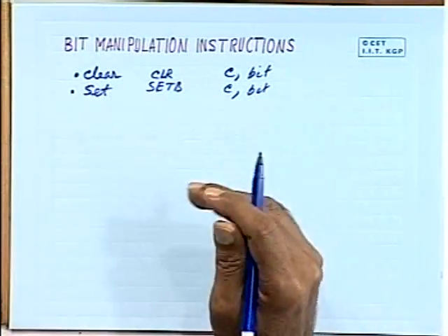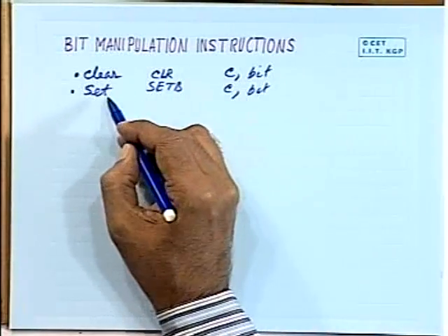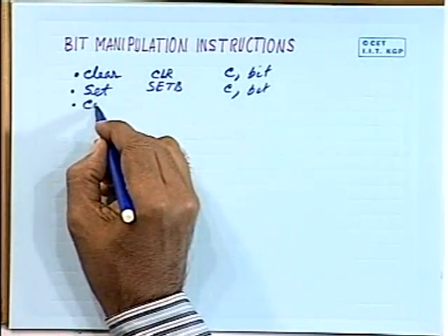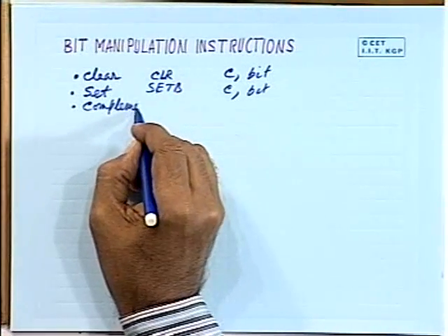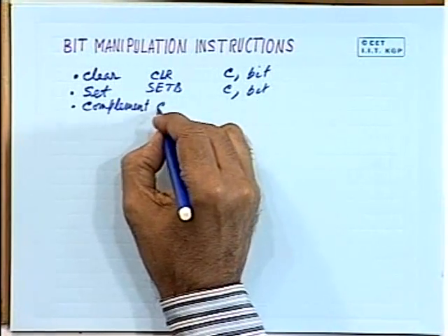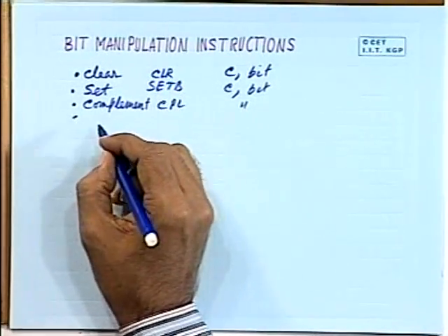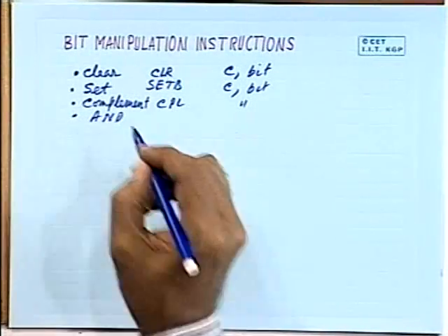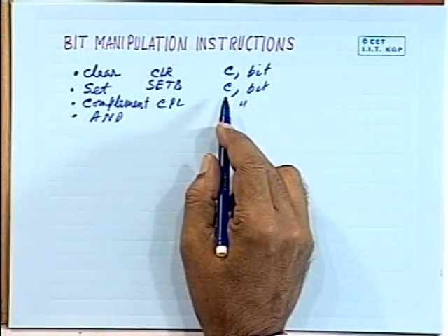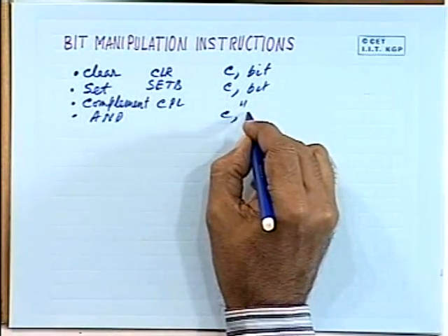We have already discussed which particular part of the RAM you can access for bit manipulation, and also which special function registers can be also selected for bit manipulation. Those bits can be cleared or set, or also you can perform complement, where the mnemonic is CPL. You can do the same thing. Then you can perform AND operation, that means the selected bit and the carry flag bit.